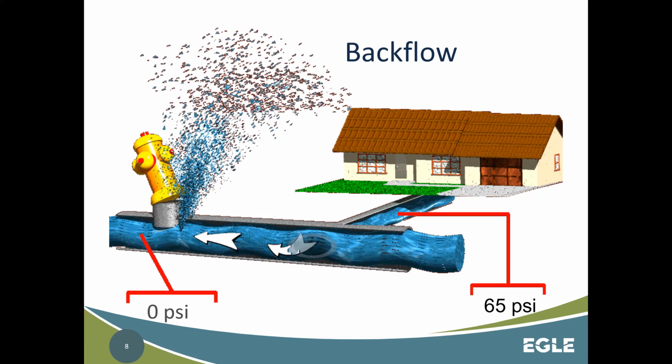But remember the example that I was talking about? If I had a Miracle-Gro can, let's say there's a Miracle-Gro can here on the garden hose, it might only affect my house, the service, or it might come out here and go into a couple service lines once this is fixed and is recharged with pressure. So that's why cross connections are an issue.